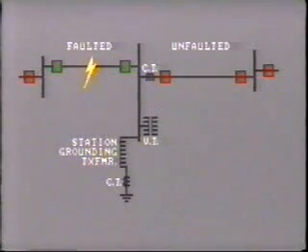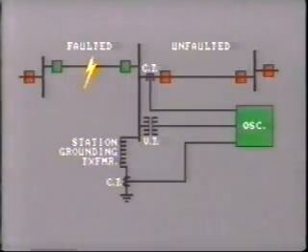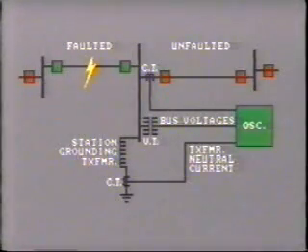In practice, this happens quite frequently when the line does not stay de-energized long enough for a temporary fault to clear on its own. In this example, the oscillograph has captured the substation bus voltages in all three phases, the transformer neutral current and line current for one of the transmission lines.